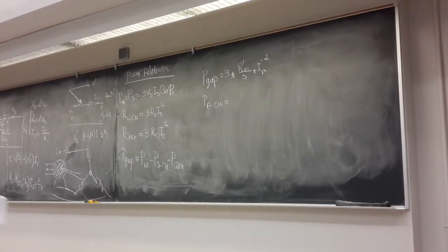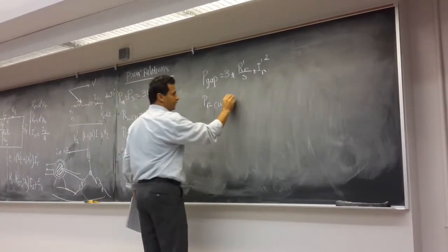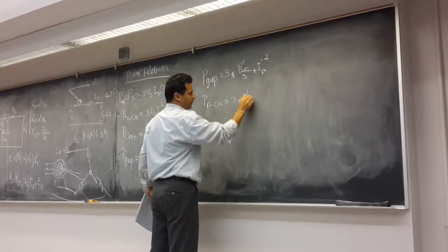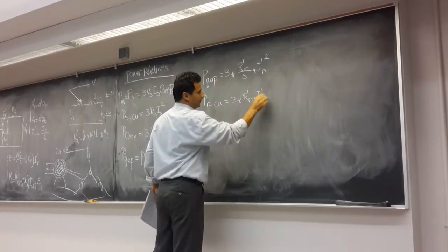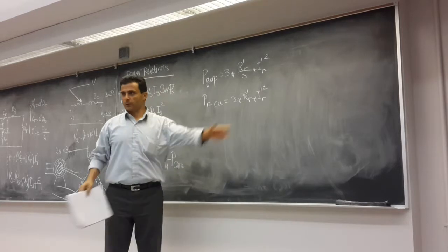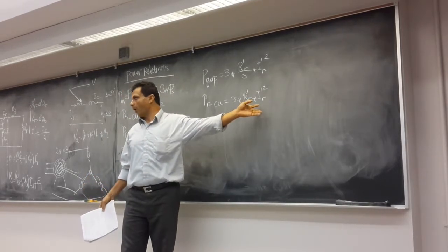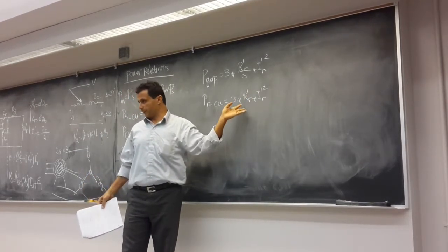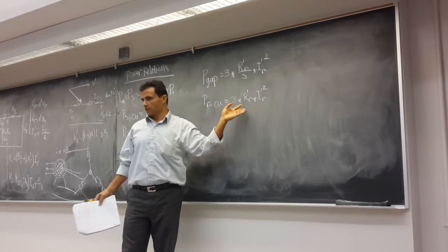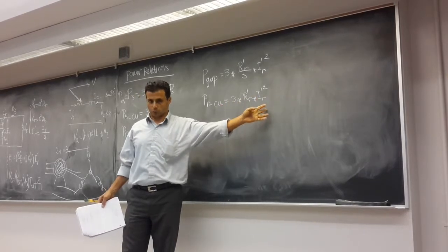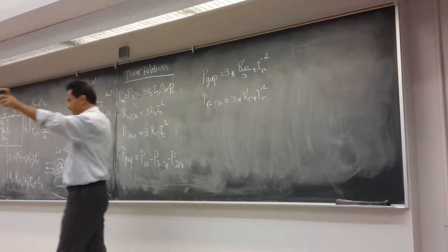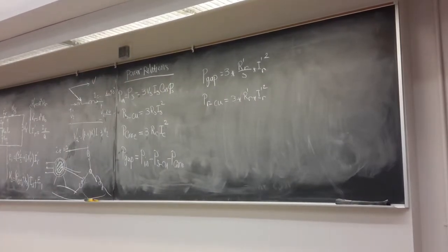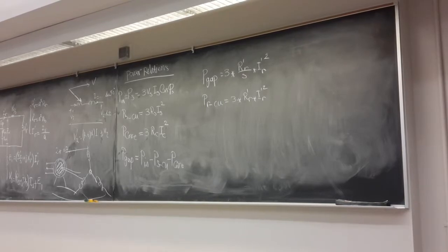It's going to be 3 times that. If the current in the rotor is I prime R, and the resistor of winding is R prime R, so 3 times that is going to be the rotor copper loss, right? Like a stator copper loss. The resistance is RS, the current is IS, so it's 3 times RS IS to the power of 2.